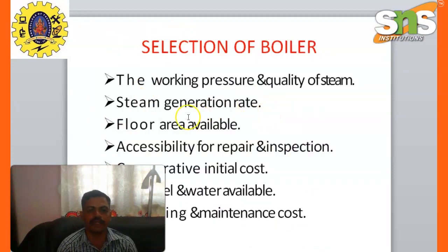Selection of boiler: the working pressure, quality of steam, steam generation rate, floor area available, accessories, accessibility for repair and inspection, comparative initial cost, the fuel, water available, operating and maintenance cost.